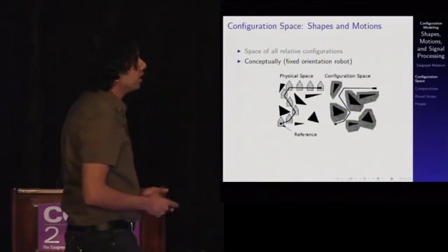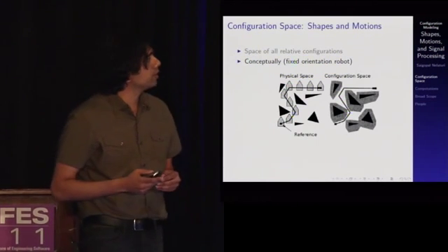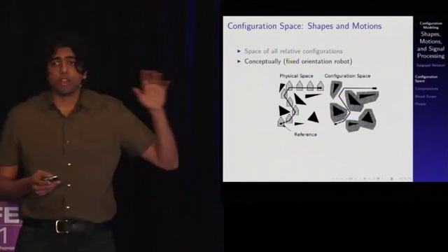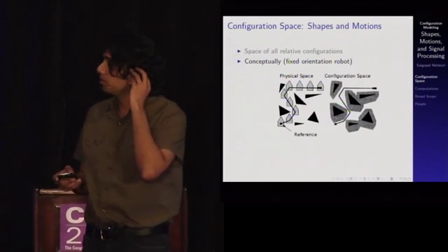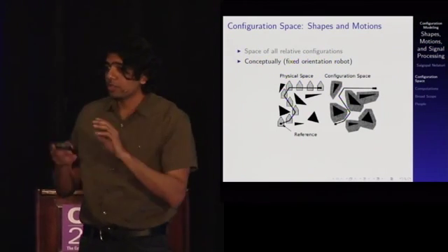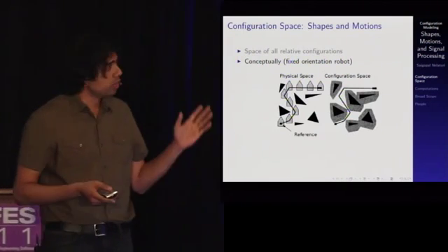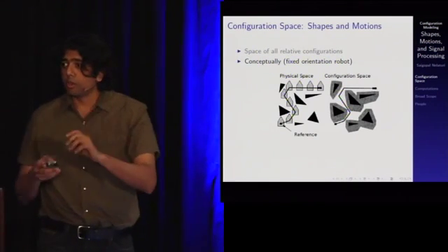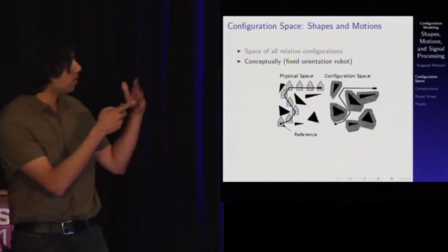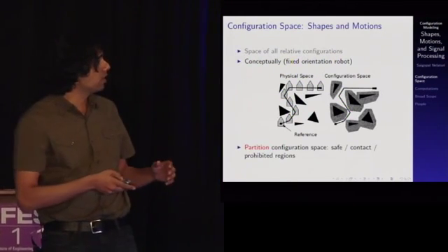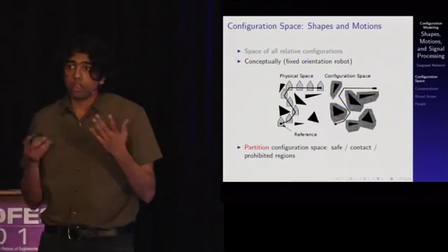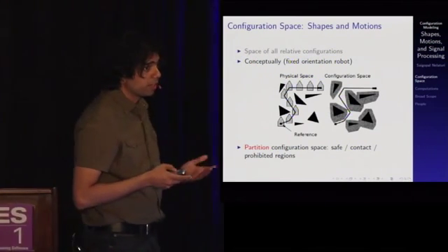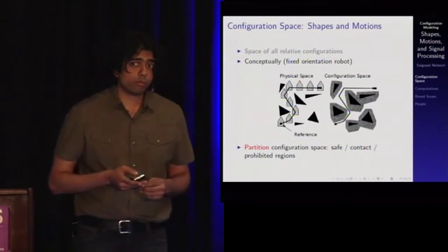Conceptually, you can look at a configuration space problem here, where we're transforming the problem of planning the path of a robot moving with a fixed orientation in the presence of these triangular obstacles to the configuration space where we are now planning the motion of a point moving around some other shapes, which are created by growing or offsetting the physical obstacles in a precise mathematical way by the shapes of the robot.